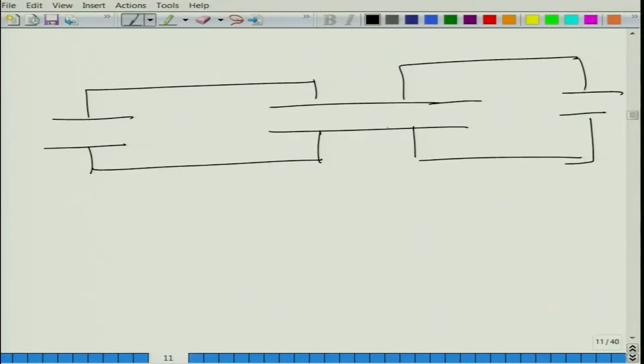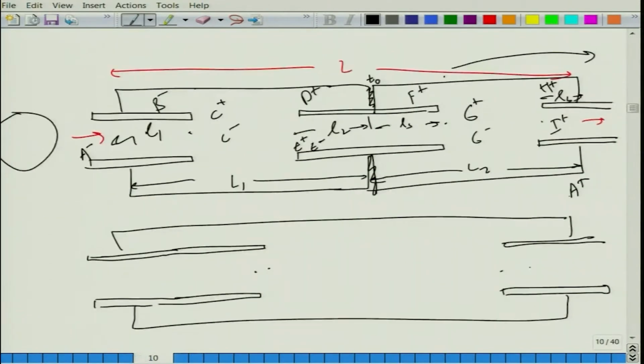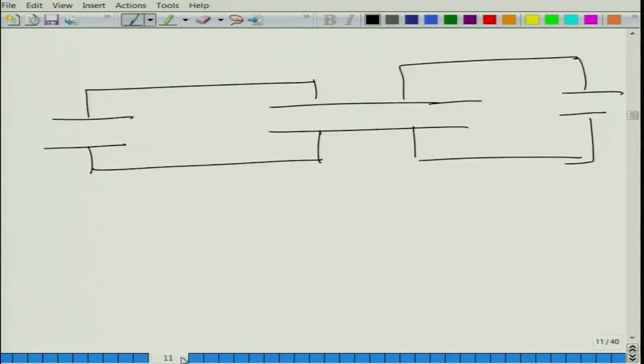And so you just have to, instead of T naught, which is the wall thickness, about 2 mm, 3 mm, consider a much larger value, whatever the length is. Replace T naught with say L dash, and the same code can very well be used to analyze this muffler configuration. So, this analytical mode matching can help you analyze a lot of things,